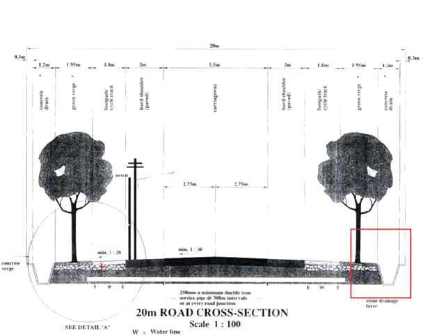Normally, the drains are open drains, unless otherwise required by the local authorities. Now, when you want to design the drain, the width is normally specified. It depends on the catchment area as well as the design peak discharge. This shall govern the depth of the drain. There should be analysis so that the drain size is adequate to effectively discharge the water.